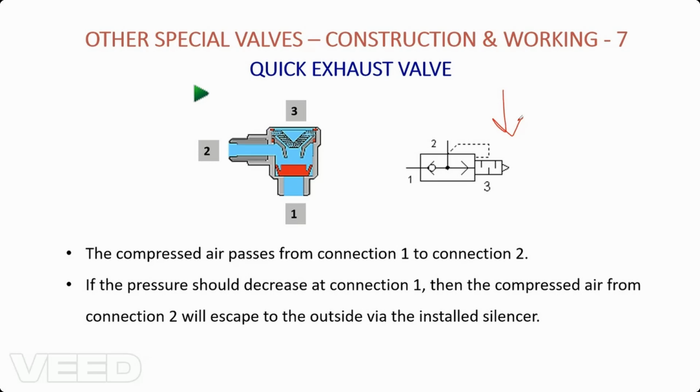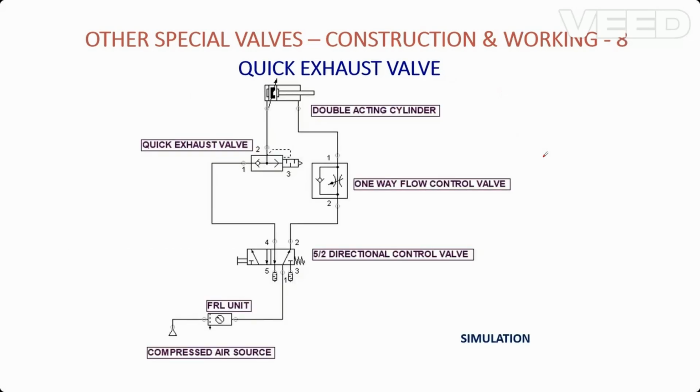At the other inlet we have connected a silencer, which supports free flow of air. So at the number one inlet we would be connecting air pressure, and the outlet we would be connecting to the component where we need to release the air pressure. So we will push air pressure into the component. When it is returning backward, the ball or the shuttle will close the inlet and make the air flow through the silencer. So this is the sequence of operation. Anyhow, we are going to see the simulation sequence in our future classes.